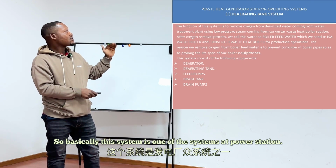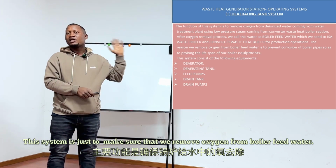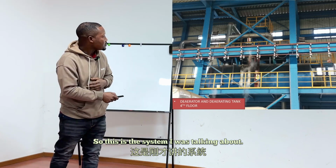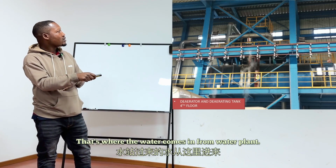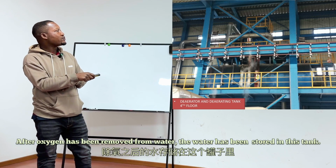These pumps pump water back to the deaerating tank. Basically, this system is one of the systems at power station. This system is just to make sure that we remove oxygen from boiler feed water. So this is the system I was talking about. This one is the deaerator on top. That's where the water comes in from water plant. This is the equipment that removes the oxygen. After oxygen has been removed, the water is stored in this tank.